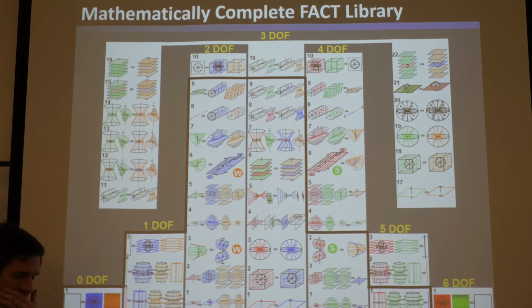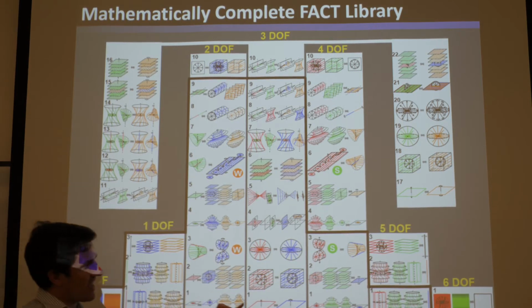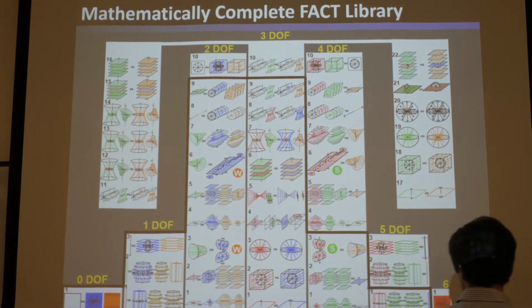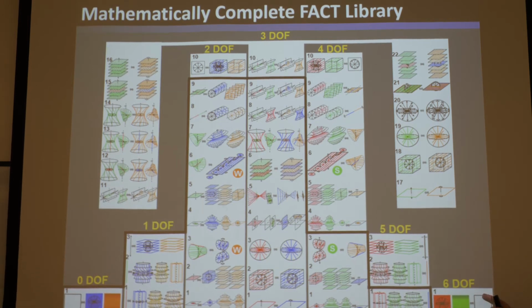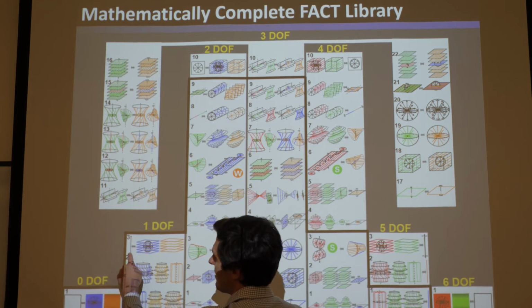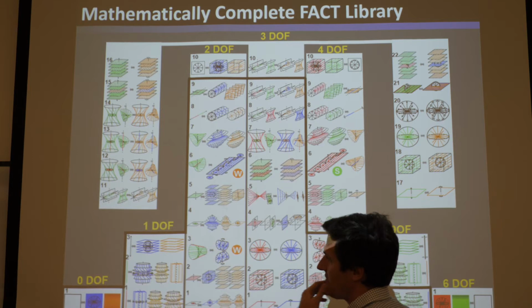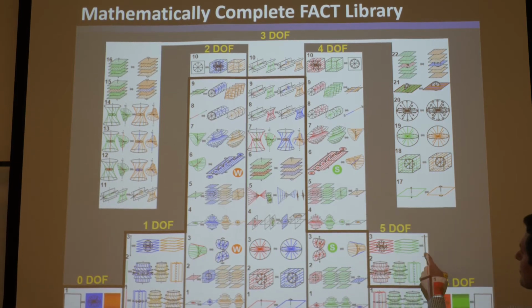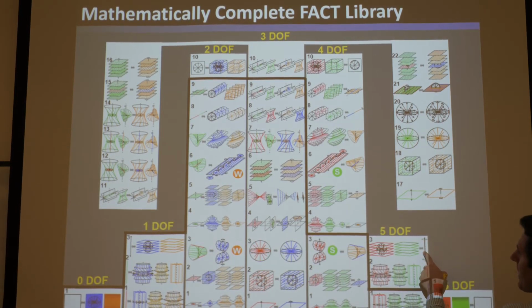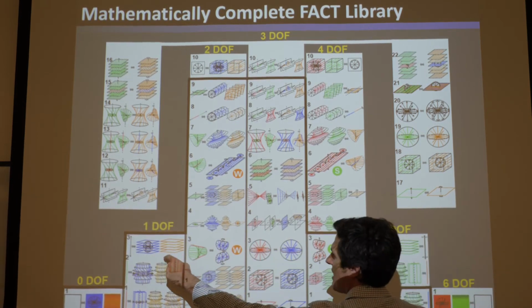And the really cool thing is you start seeing that, holy cow, check out this freedom space here that's empty. 0 degrees of freedom is obviously the same as the constraint space over here that's empty. If you have 6 degrees of freedom, you have no constraints, and therefore its freedom space is the same as its constraint space. Then you look here and you say, my goodness, look at this translation, which from that previous slide, translations are analogous to pure moments, and blue lines are analogous to red lines, and green lines are analogous to orange lines.